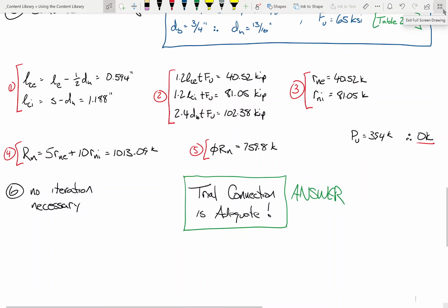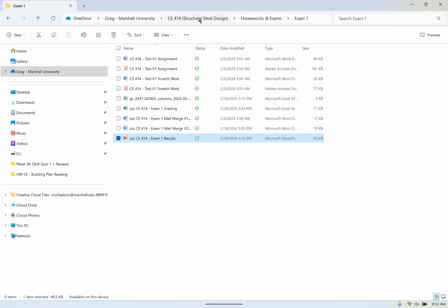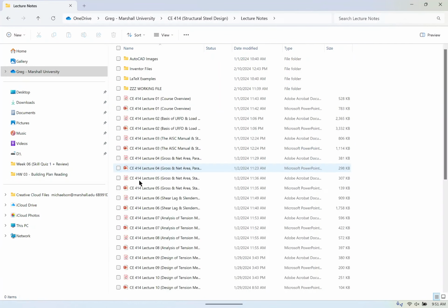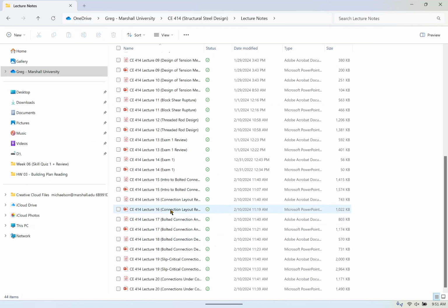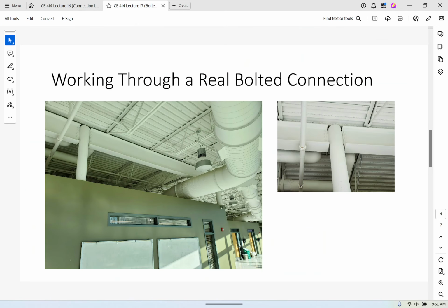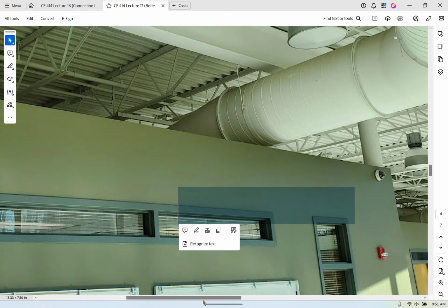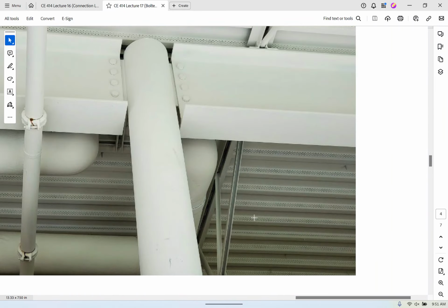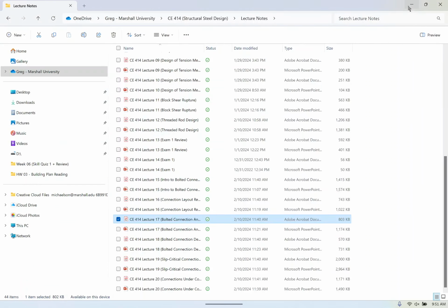If we go back to, I know we're running out of time, but I'll be quick, these connections here, the more this connection gets spaced out, the more plate behind that web has to exist. That's more money that may not be necessary. So we want the connection to be as compact as possible so that we can save our clients some cash, but it's also obviously got to be safe.